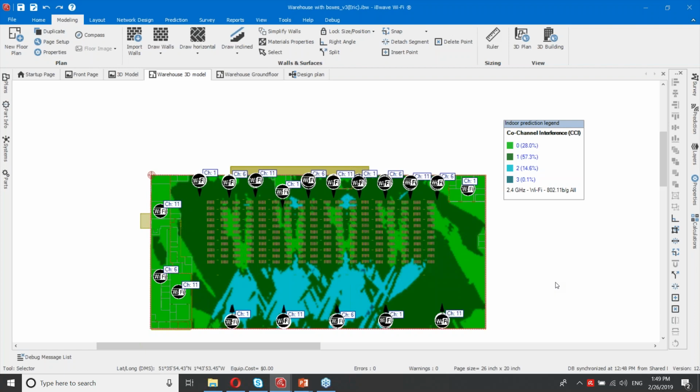You do want that antenna to be above the machinery that passes through, or the machinery that can be parked along the side of the wall. So that's why I would go with 2.5 meters or even 3, and then down tilt later on to improve the coverage at the lower points of the shelf. Remember, you do need to cover shelves maybe higher than what I have shown here.